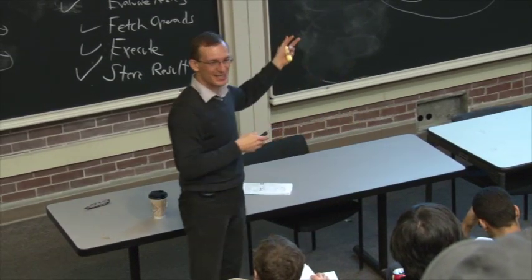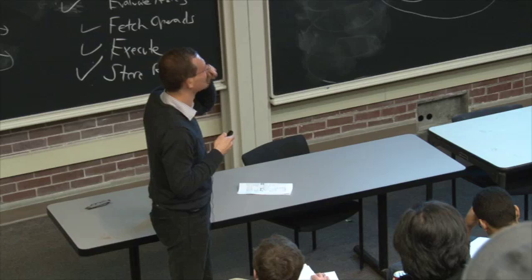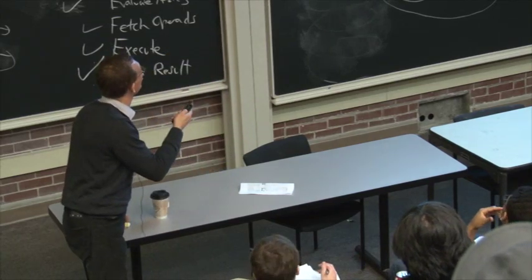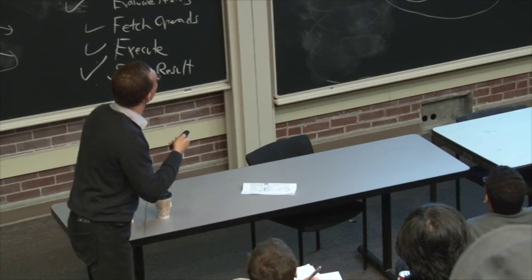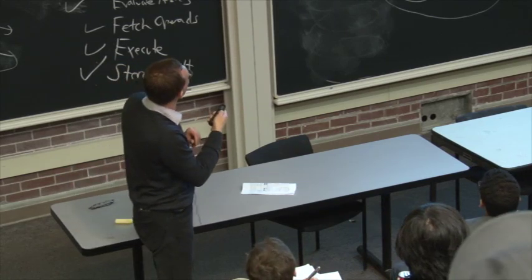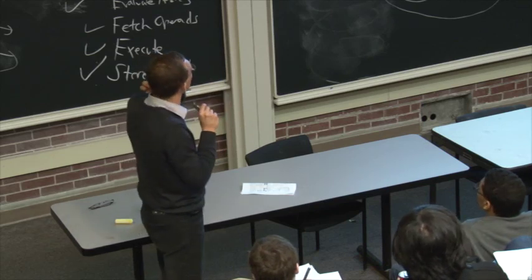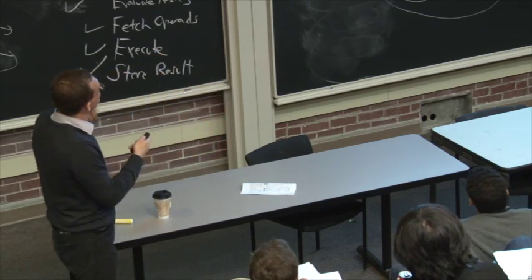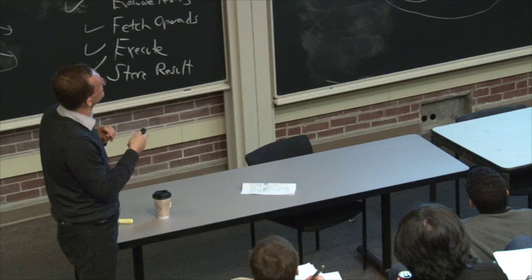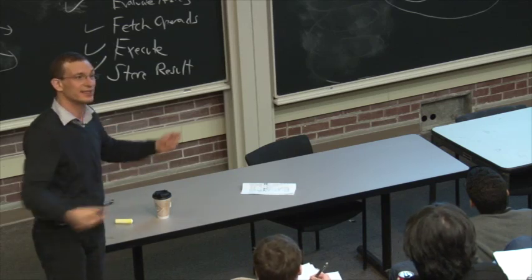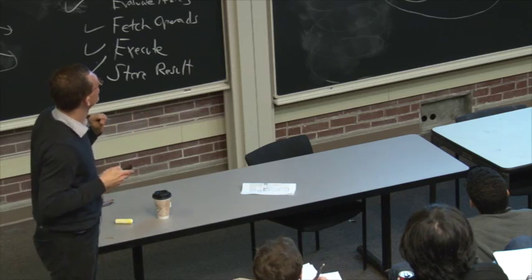When is this a bad design? Most of the time this is a bad design in most realistic scenarios. So how can we design a better microarchitecture? And you know the answer to that, right? So let's analyze. Every instruction takes 1 cycle to execute. So CPI is strictly 1. Remember the CPI, cycles per instruction. And how long each instruction takes is determined by how long the slowest instruction takes to execute, even though many instructions do not need that long to execute, right?